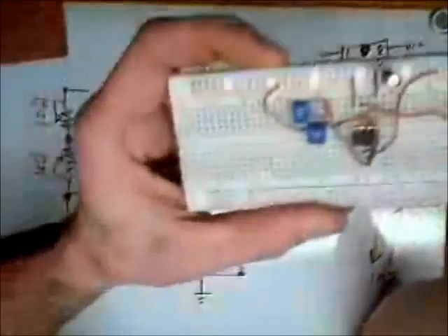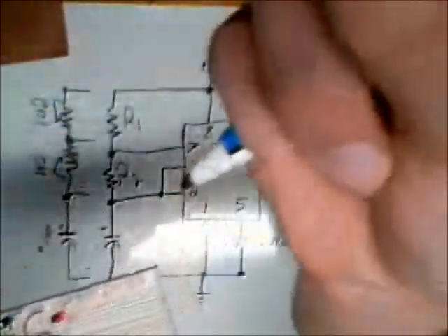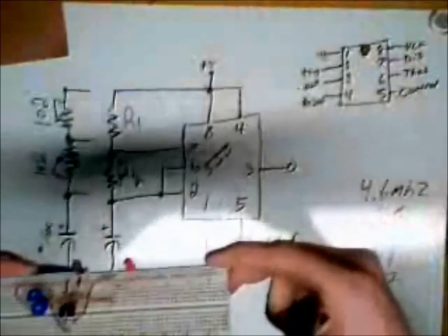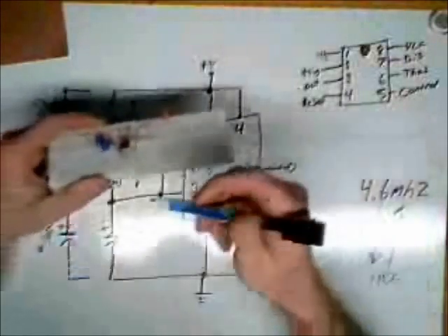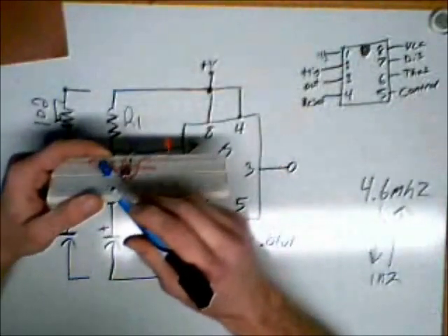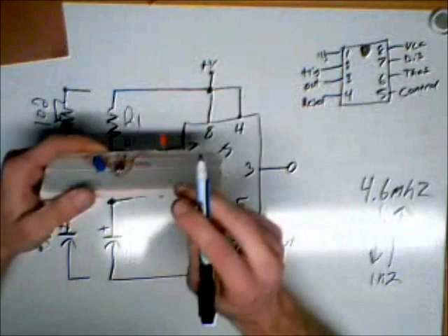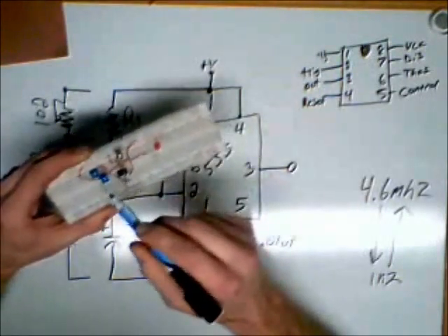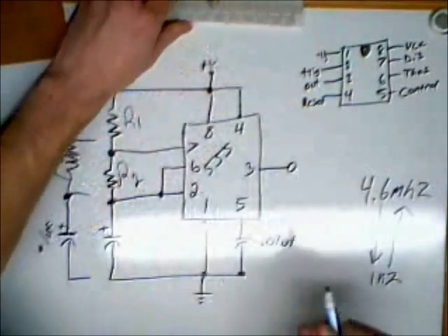We're going to be using two 102 trim pots. They can either be blue or the ones that look something like that, with a little top on them, and they'll have a little number. 102 is the one we're going to be using, and what that means is that you add 2 zeros to the end of the 10, so that's going to be 1000. So these are both 1000 ohm trim pots.